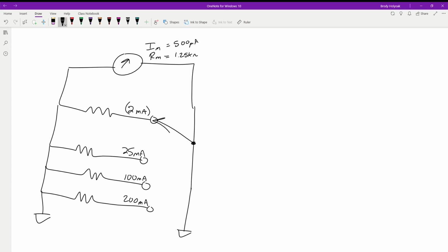Thinking about this, even on the initial range, 2 milliamps is going to do what to that poor meter? If we allowed 2 milliamps to go through it, it's going to peg it and bend the internal workings, so it's not going to read or work right ever again. Like you guys are starting to figure out with some of your meters. I'm being serious.